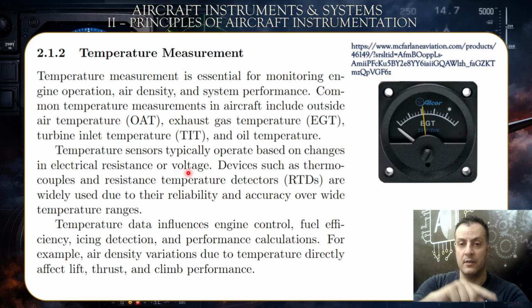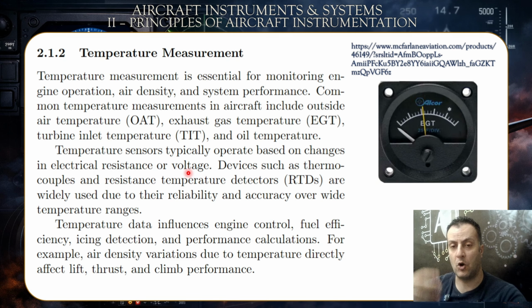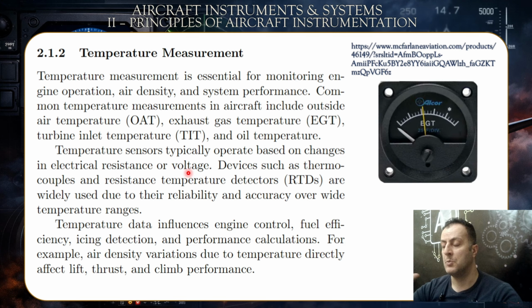So you have, during cold or in normal operating conditions, the material, which is, by the way, made of conducting material that is stitched together, okay? So during cold weather or normal operating conditions, when you have a low temperature, the molecules of this substance are stuck together, which is a conducting substance, by the way. So the current would go easily. It would act as a short circuit, conducting the current perfectly.